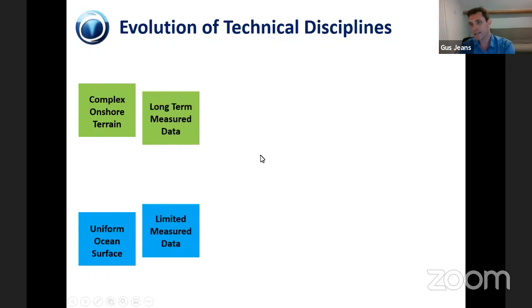Also, historically, in the wind resource and wind energy onshore tradition, you would be able to find some long-term measured data at some sort of reasonably representative location. You would have to make corrections to that, and established techniques were developed to correct a long-term reference data source to your particular location, taking into account the large variations due to the terrain primarily, but also other factors.